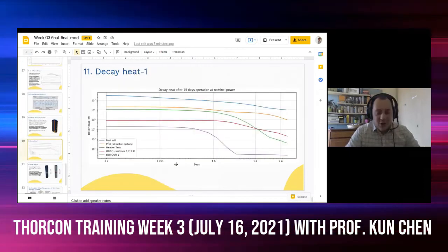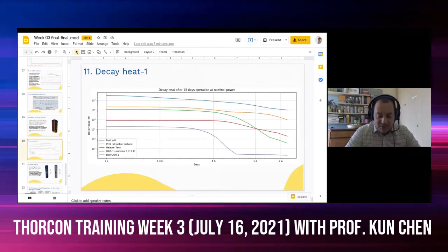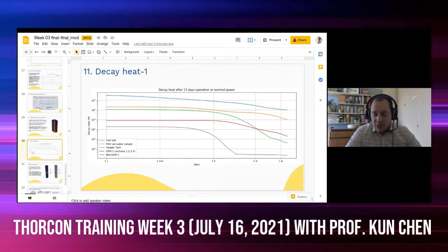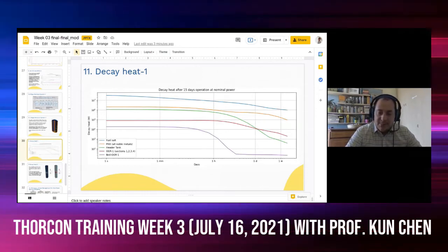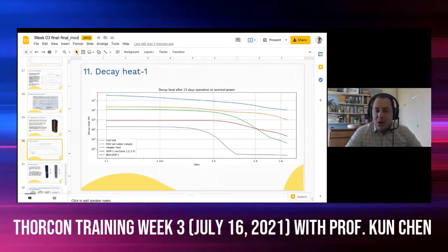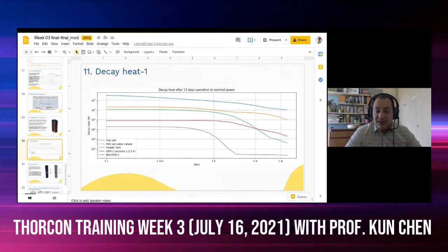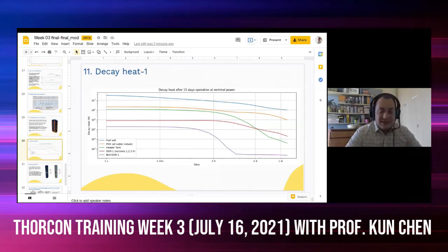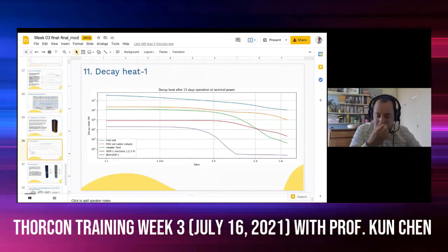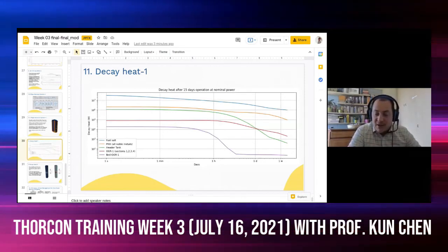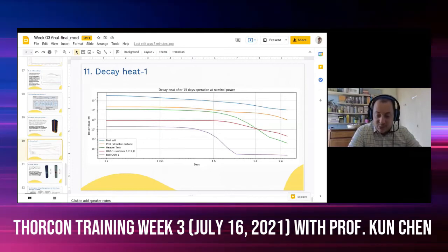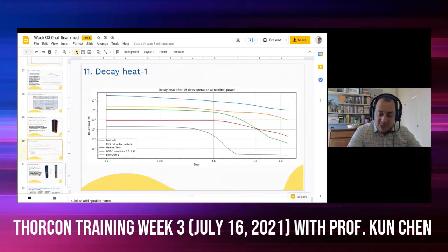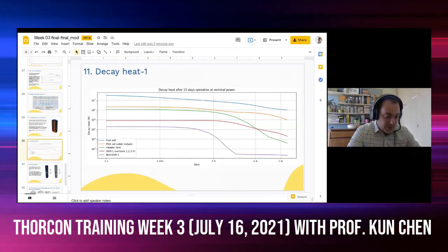Differently from a solid fuel reactor, we have the advantage of being able to continuously remove the main source of radioactivity in case of accidental release. That is related to the fact that we can remove gaseous fission products, so we have a much reduced source there.